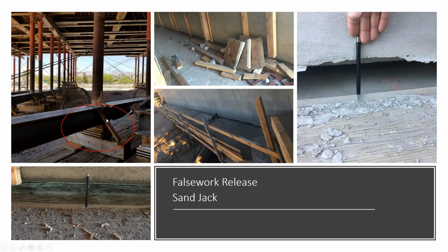I can show some pictures of how they were releasing the falsework by breaking these sand jacks. And after that, you can see how the falsework dropped immediately.